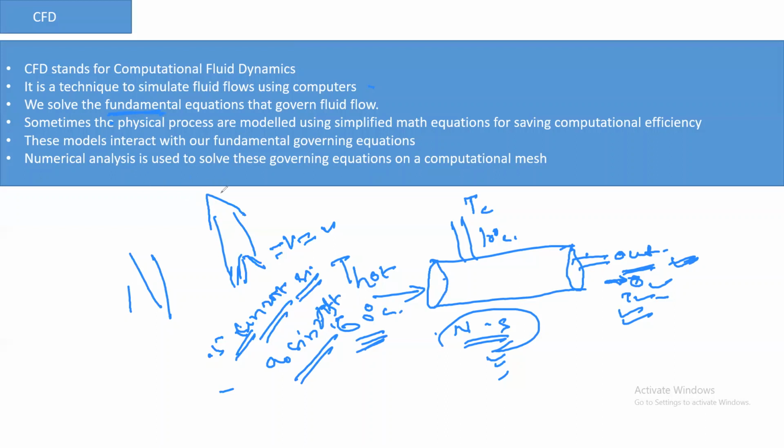By now the physics is pretty complex. By adding some physical process, you have to model this problem using a UDF. There is a concept called UDF, user defined function. By making that, you can simplify the problem and make the computation efficient. Otherwise, if you are not doing that, it would be very difficult, and sometimes impossible, to do. So very complex physics you can simulate in CFD.